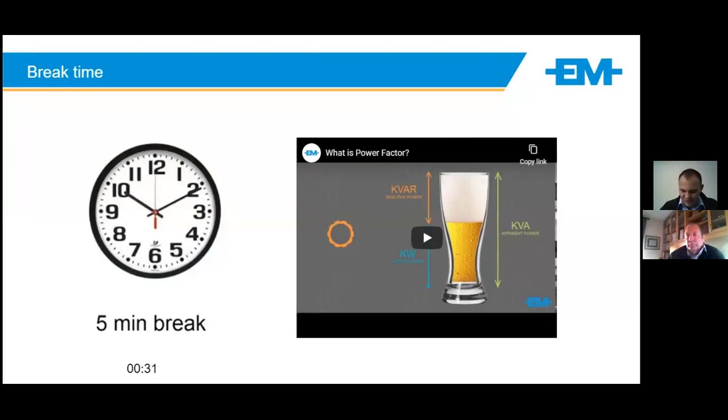So as we said, the current harmonic contributes to the voltage harmonic. The higher that THDI is based on the total load of a transformer, the worse your voltage harmonic is going to become, and the worse the total effect is for your site. But to shorten it and just give you the answer, we typically say THDI no greater than 10%, and voltage harmonic no greater than 2-3%.